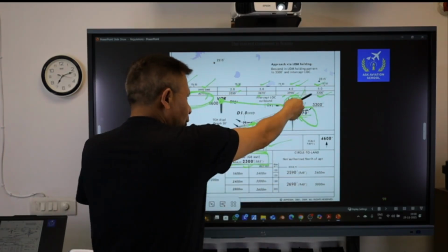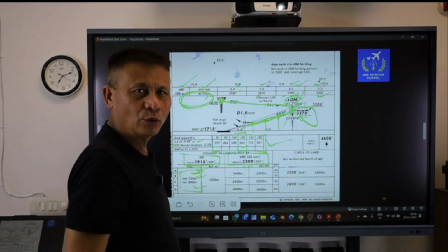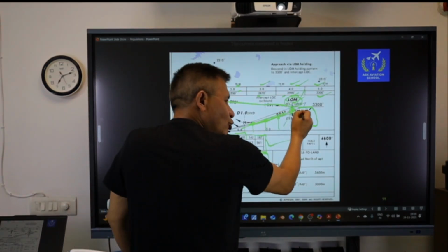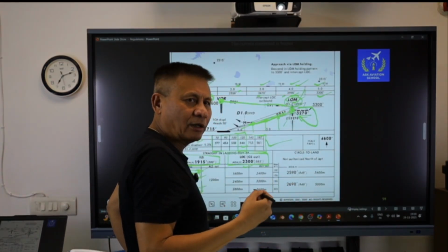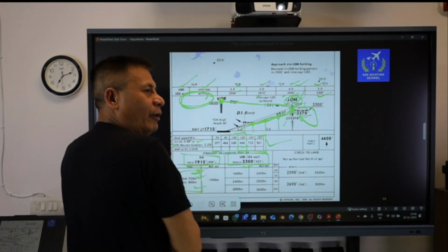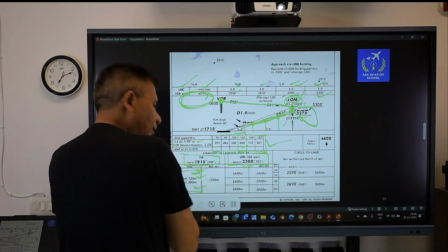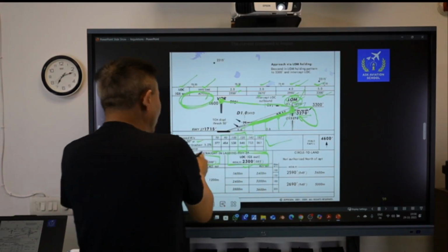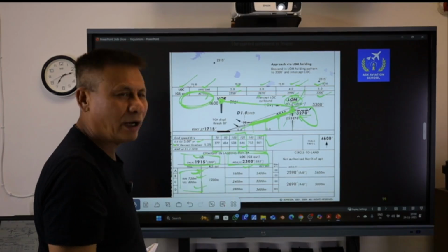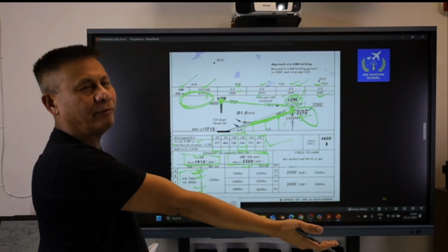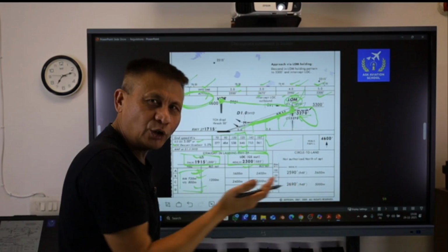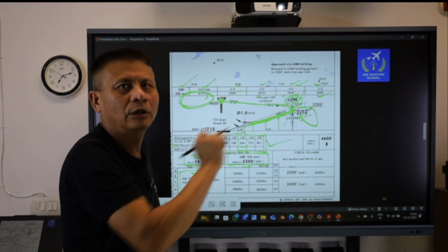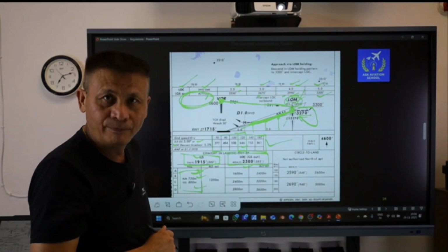You are not authorized to continue the approach. But however, after having crossed these 2 points, or after establishing the final approach segment, even if the weather minima goes below the printed, prescribed minima here, then you can continue till the time you reach your minima, that is 1915 feet. At 1915 feet, if you are able to establish the visual reference, you will continue the approach, and if you are not able to establish the visual references, then you will carry out the missed approach procedure.